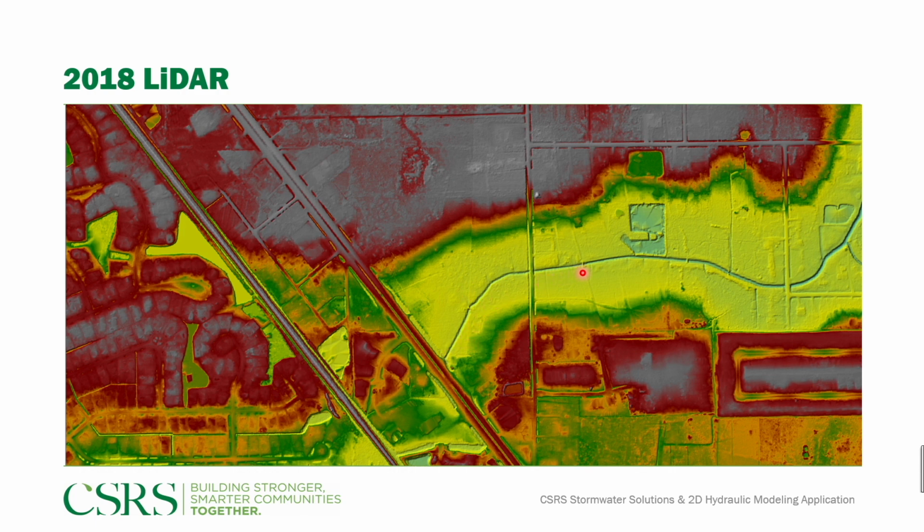Now, it's important to note that the LiDAR technology does not penetrate below the water surface. So if the day they flew it, whatever the water level was, it's not going to get any elevations below it. However, in the hydraulic computer models that we use, we need to know what's below the water, because that's important for a lot of that water to flow downstream.